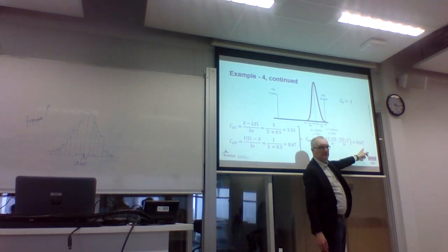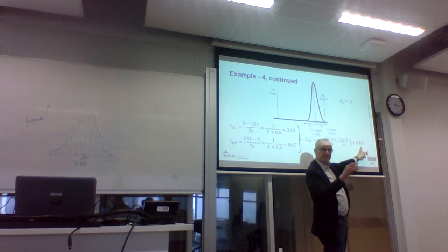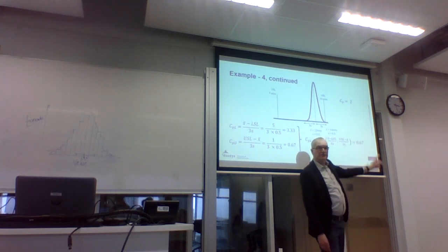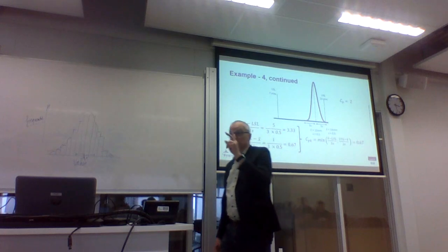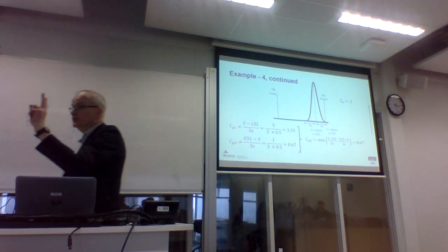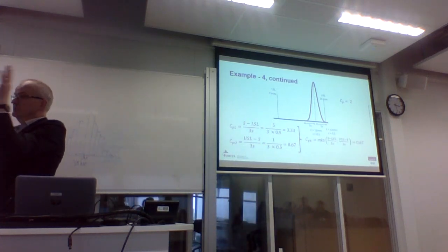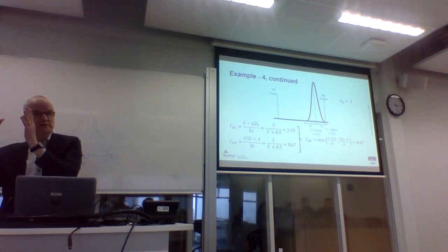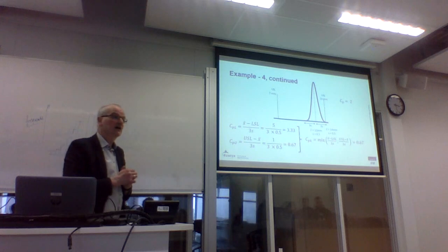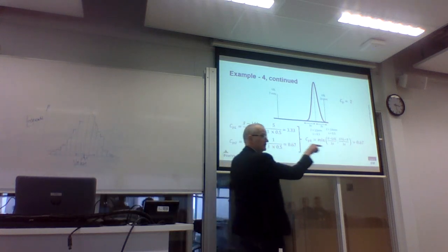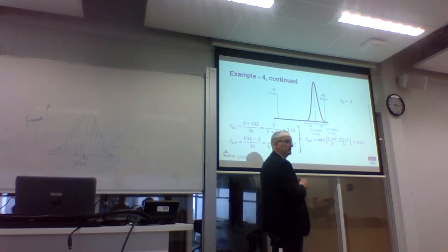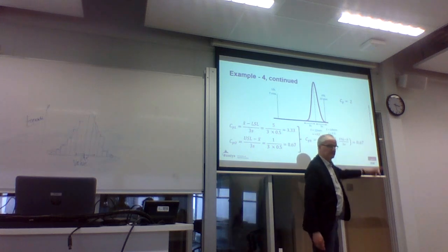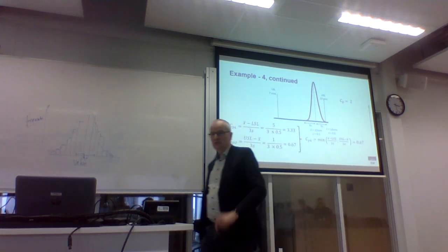and that tells me something about how accurate I am, how far away I am from the average. And this shows that my CP is still 2. Remember, CP is still 2. That's good. I don't have much range, much variance in there. That's pretty good. The only thing is, whoops, I'm on the wrong side. I'm on one side. I have a problem on the upper limit. That's what it says. 0.67 is below 1, and you don't want to be there.